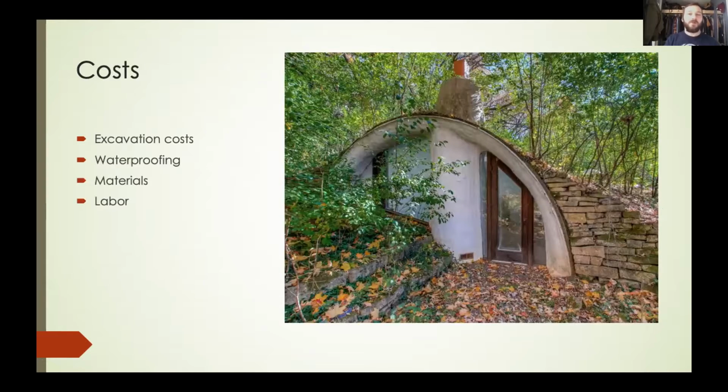So our overall cost, as I kind of discussed, your excavation, your waterproofing is going to be another significant initial cost because you're going to be waterproofing the entirety of your structure or the majority of your structure, whereas a normal structure, as far as waterproofing masonry, you're just looking at your foundation.